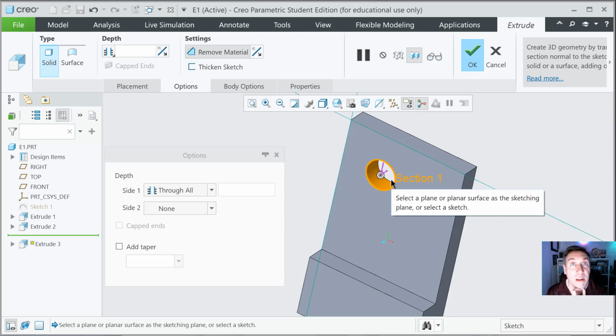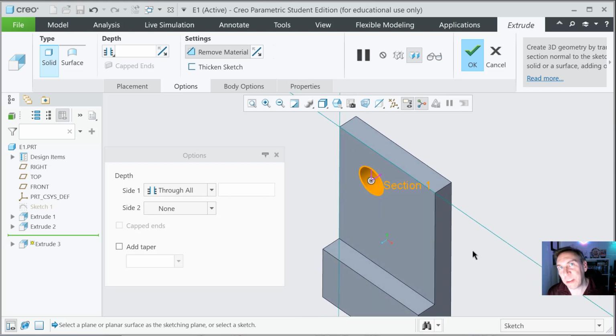So that's something called design intent. And that was something I remember them talking about in my training years ago in the 1990s. And it saves you time later on, and it helps the next person who might open that model so they don't make any mistakes. Because you're like, yeah, well, 1 hole, I would see that, right? What if it's a part with 1,000 holes and you miss that? And then it goes out into production. All of a sudden it goes out to the customer, and they're like, wait, these aren't cut all the way through. That's the idea of design intent.